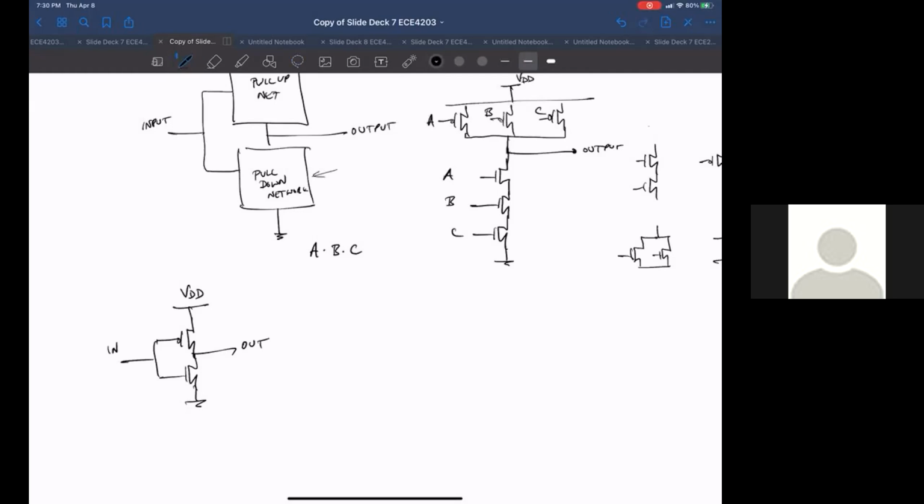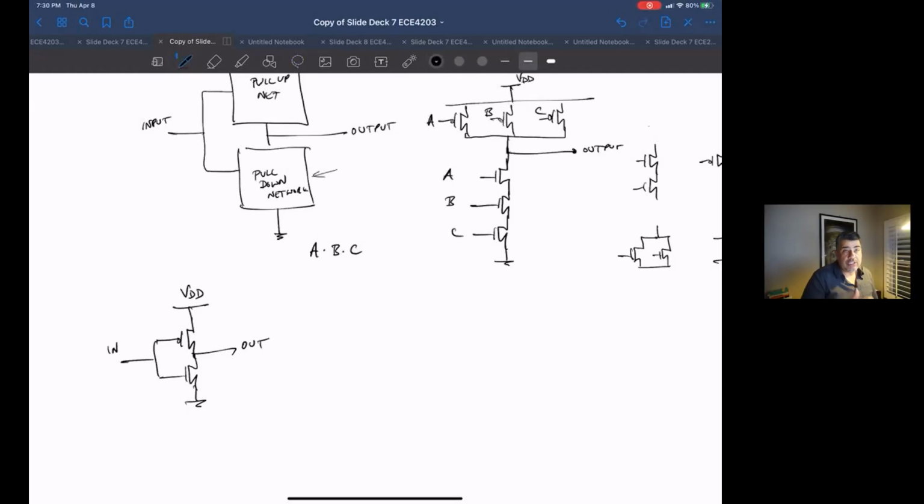Yes. So then a unit inverter is, now you have to remember some of the stuff we did before the break, which is difficult. A unit inverter is when the NMOS is the smallest device you can get in a process, or we call this a 1X. That's code name for the smallest device in a process.